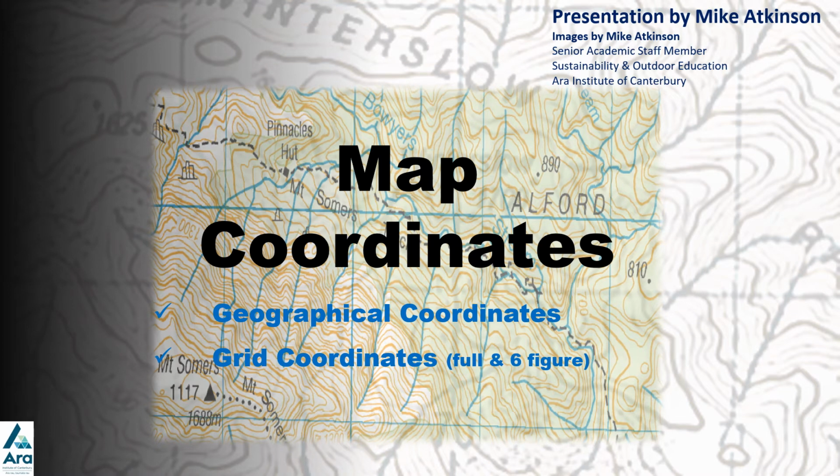This video is going to look at the different ways to present or express map coordinates. There are two main ways of showing map coordinates, either the geographical coordinates through latitude and longitude or through grid coordinates. And there's two ways of expressing those, full grid coordinates or a six-figure. Now there are separate presentations for a six-figure grid reference, which is probably the most common way, and there's also a separate YouTube clip on looking at geographical coordinates. So this presentation is giving you an overview, and then for more in-depth information, go to those other presentations.